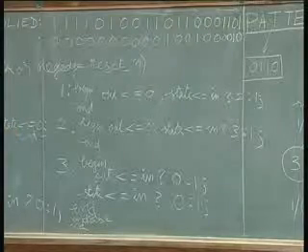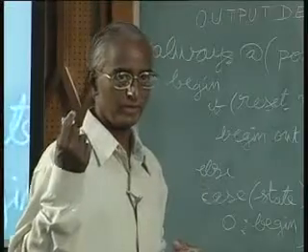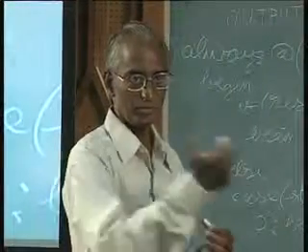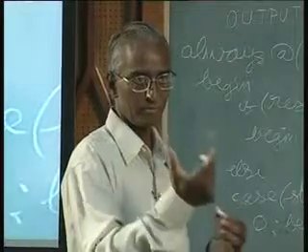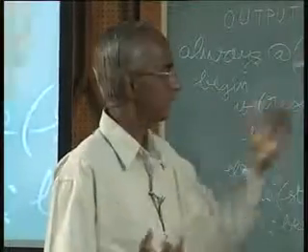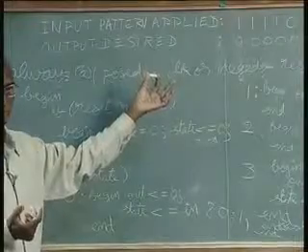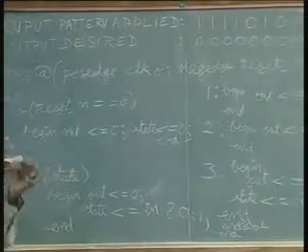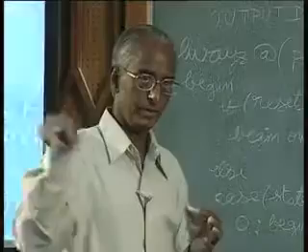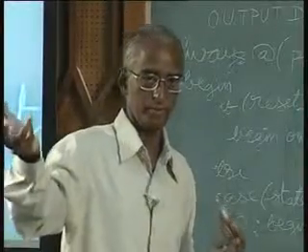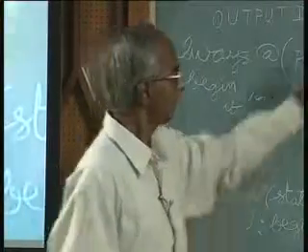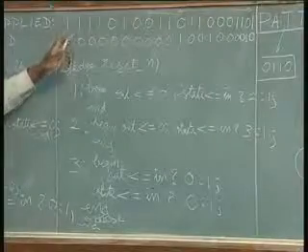So what we can do is mix. We have already seen how to use the shift register in the previous example, parallel to serial conversion. That is precisely a very handy application here, isn't it? So you as a user can give, let us say, 16 bits and put them in that other module we have already done, and then serialize, and that serialized pattern is what is applied here.